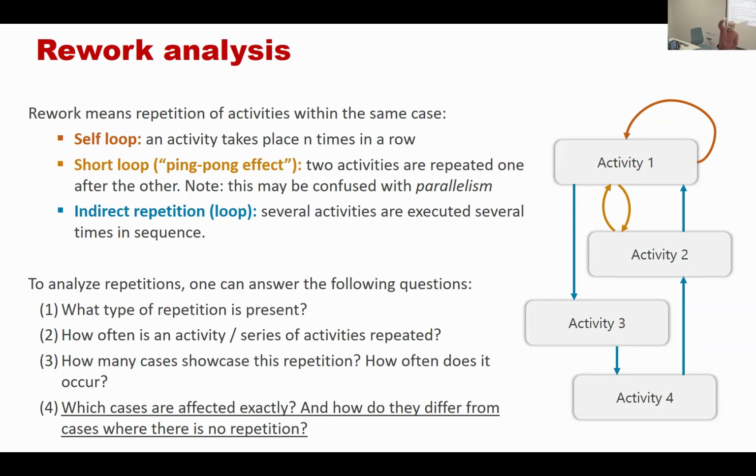And then sometimes you see repetition involving a longer sequence of tasks. So we will be looking for all these 3 types of rework: direct rework; indirect rework, where you do an activity, you quality check, you go back, or you do an activity, you repair a defect and you go back; and also longer loops that might signal situations where you had a defect, you did a few other activities, and then you discovered that there was a problem and you came back.